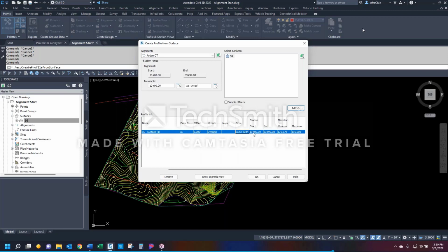and you'll know real fast if your profile is going to fit your alignment or not. If this is shorter than your alignment, that you know is some 3,399 feet long, almost 4,000 feet long, if this says 1,000 to 2,000, yet you know my alignment is longer, then there's a problem. It's going to tell you minimum and maximum elevations along the surface that it already sees.